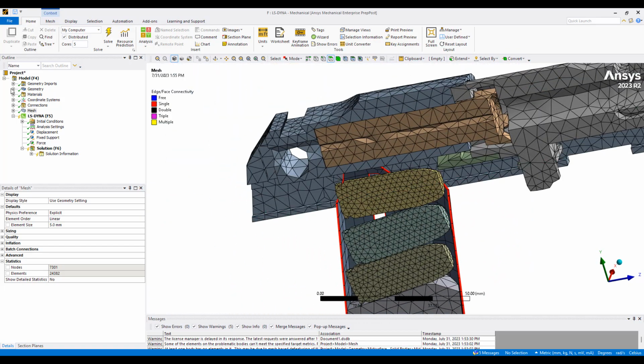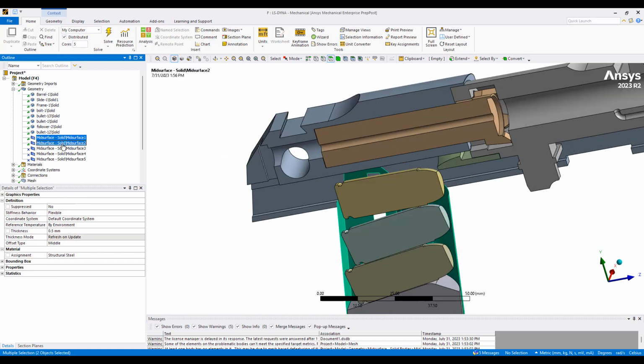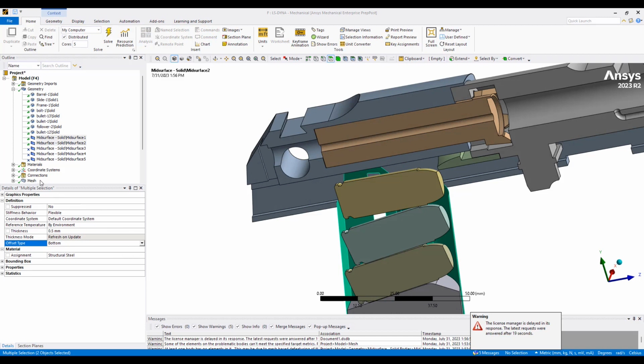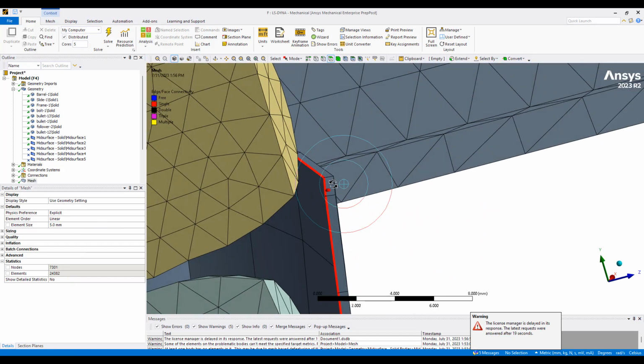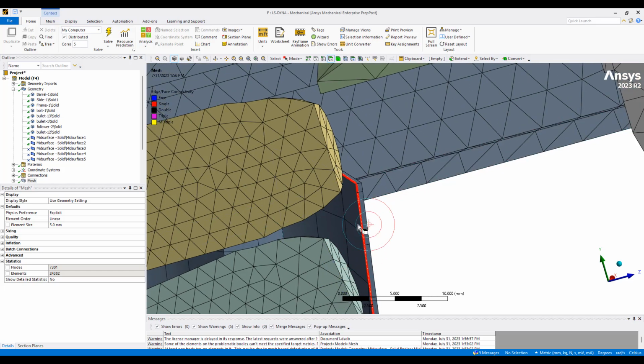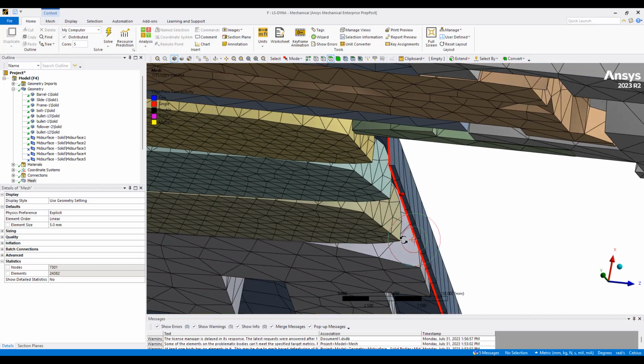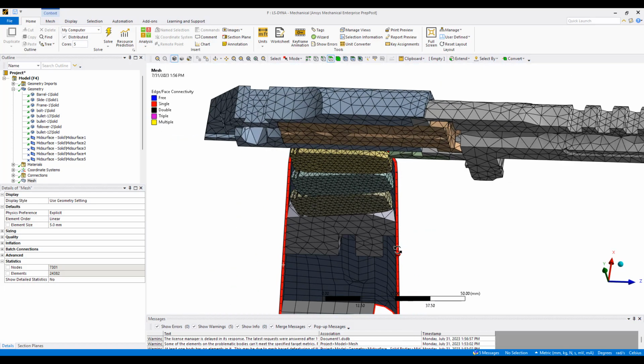boundary. So one way of adjusting this is finding the mid surface, and we can choose to put it offset in the middle, bottom, or top. So if I change this, then the mid surface becomes the bottom of my surface, and that means the mesh goes on the other side. That gives us a little bit of room for the mesh to move.